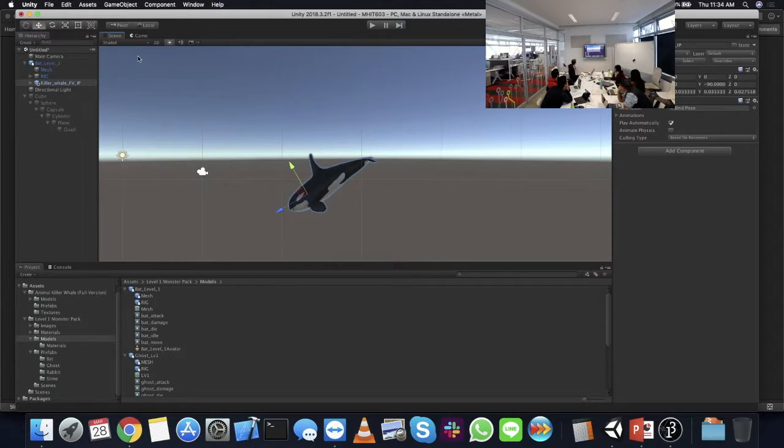But what I can actually do is we'll see up here this little thing which says local. And if I move onto it, that's a very confusing tooltip. But what local does is it basically means move it in the local space. So move it relative to its place in the hierarchy. So if the bat's been rotated 30 degrees and its x-axis points in this direction, all of my tools will also point in that direction.